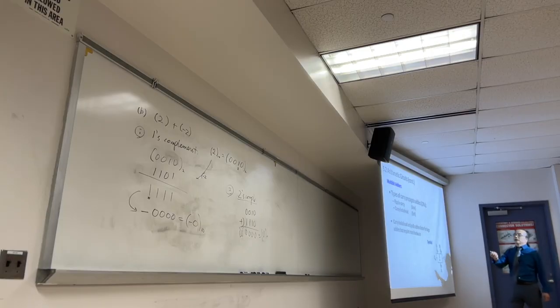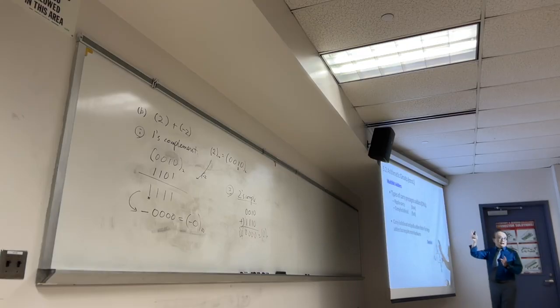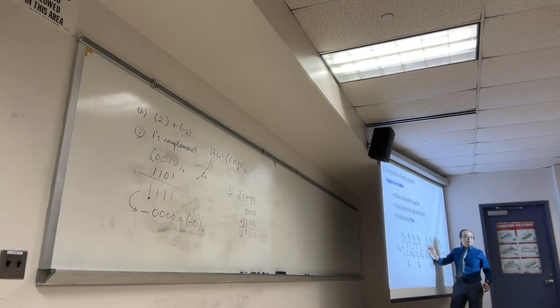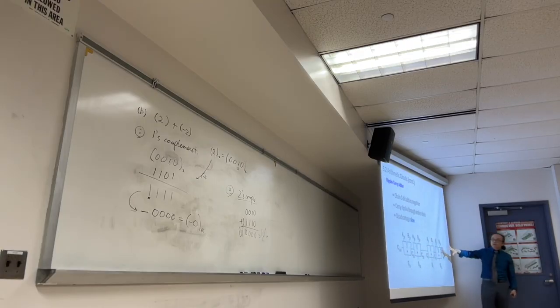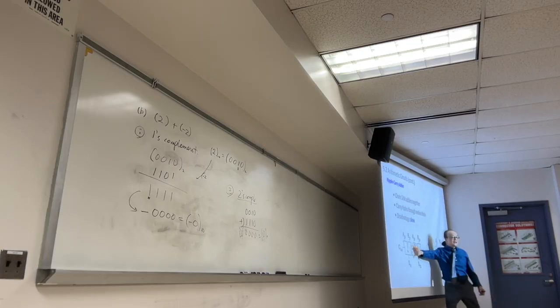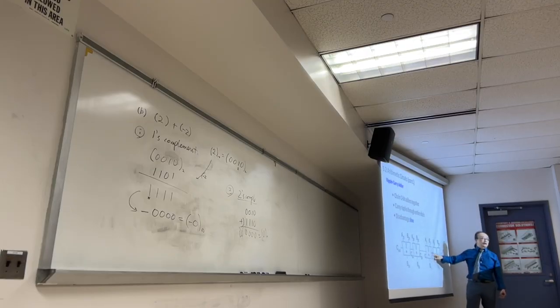So this is half adder and full adders, and there are more adders. So ripple carry and carry look ahead. I just show you the diagram, and you don't have to worry about these two. So ripple carry, so you have the bits. If we have a 32-bit 2 registers, you're going to add them up, lowest bit, put it in, put it in, put it in. But these guys cannot calculate until we know about the carry, right?